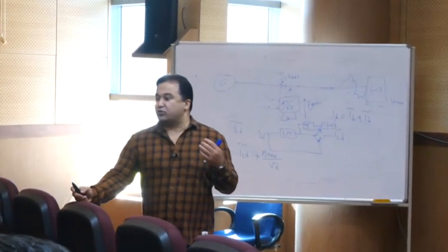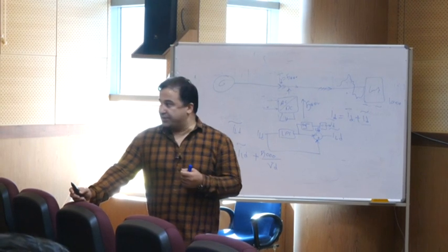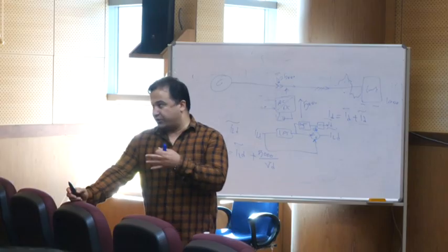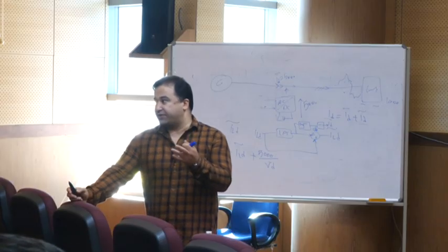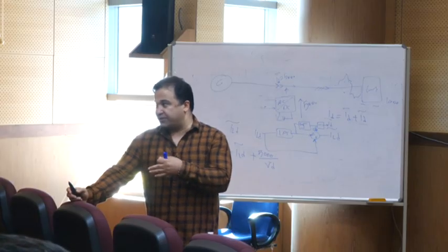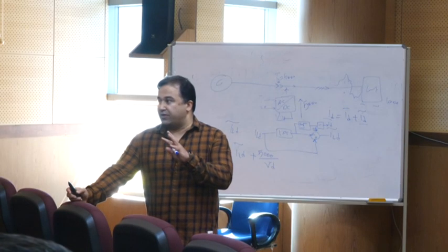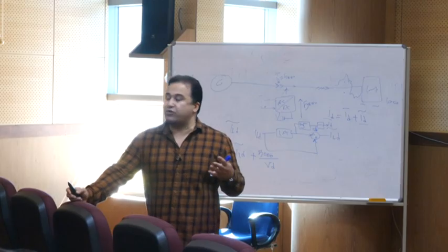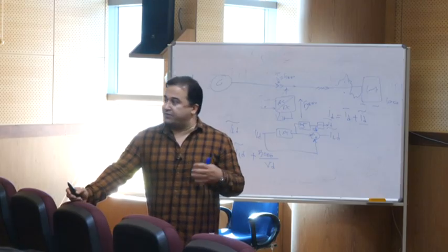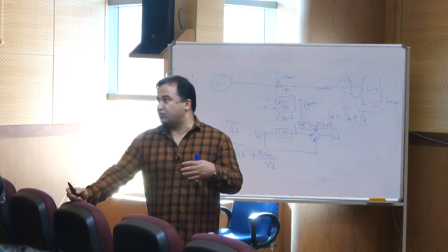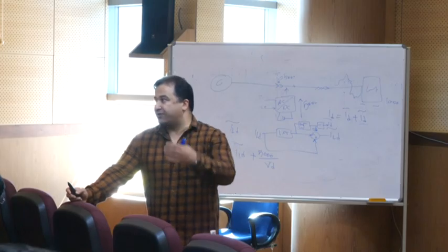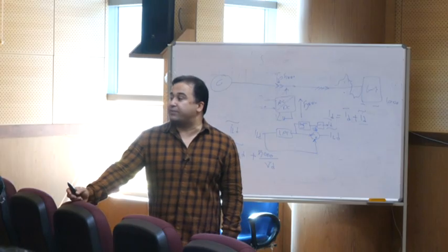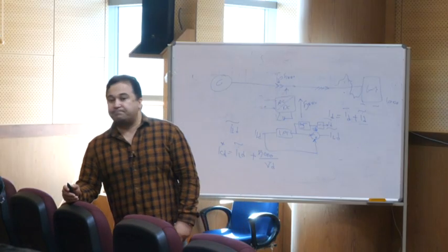So if you are going to compensate, it can be active power in harmonic frequency, reactive power in harmonic and fundamental frequency. Then if you have more possibility to inject, or enough available power, you can think about injecting some active power in fundamental frequency, so that you don't pay a penalty.